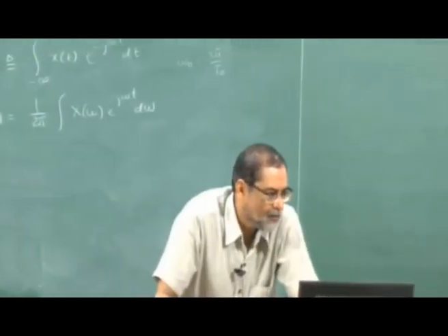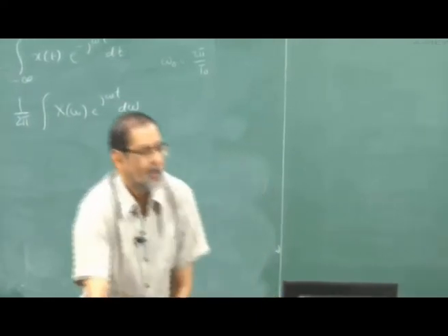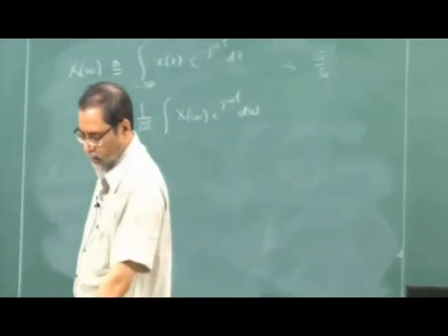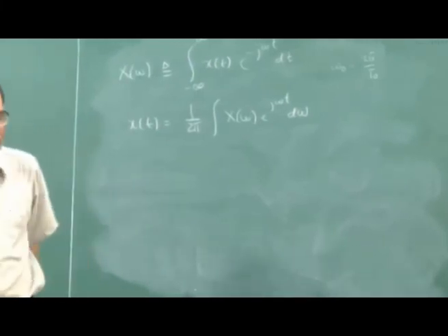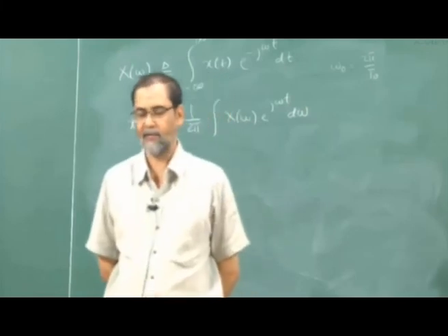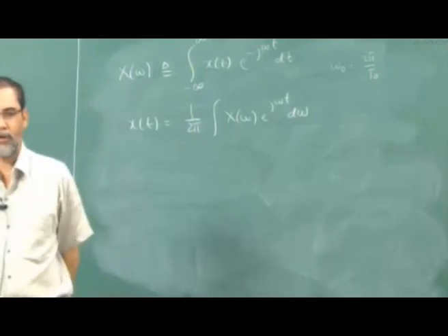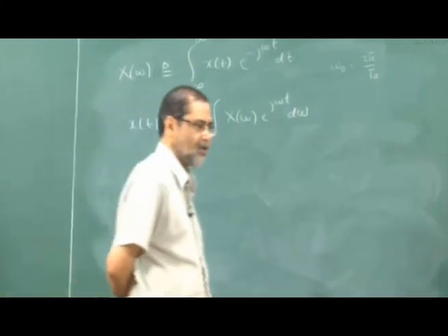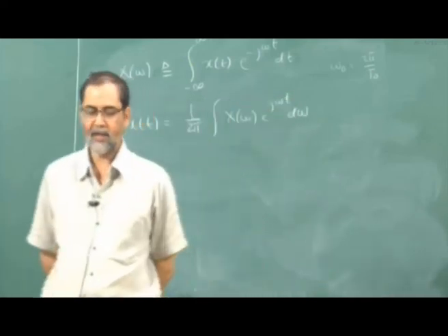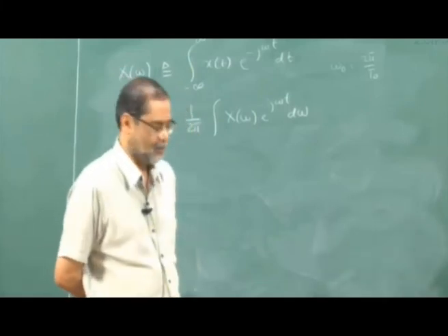Is convolution possible for a non-LTI system? Since non-LTI systems have impulse response? No, right. First of all, convolution is defined only for LTI systems, right. That is the point we made in deriving the result for convolution. We used the features of linear and time invariant. Okay, so to answer your question emphatically, no, right, only LTI systems have convolution.